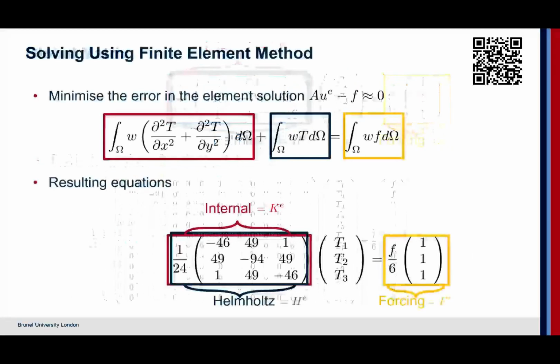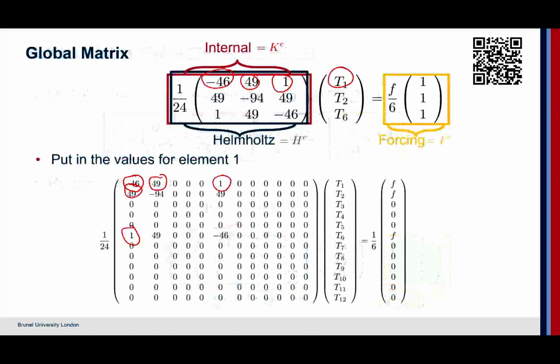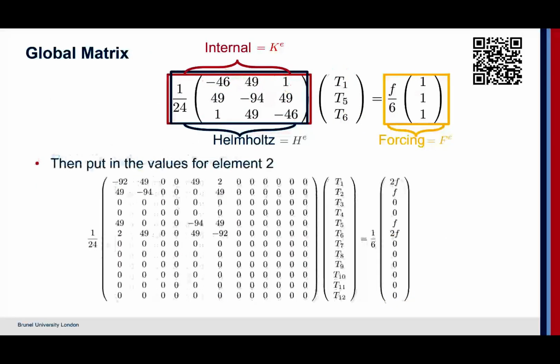You're going to do this in code, within Matlab, but the process really is: get the local elements and then put them together in the global matrix using a loop. You might find that one of the tricky steps, actually working out exactly how you loop through and collect the global ones in the correct way, but essentially it's a problem of indexing. Bear in mind in Matlab you can do the same indexing you'd normally do. So you can take elements i and j, for example, of the K matrix, and put them into the global matrix.